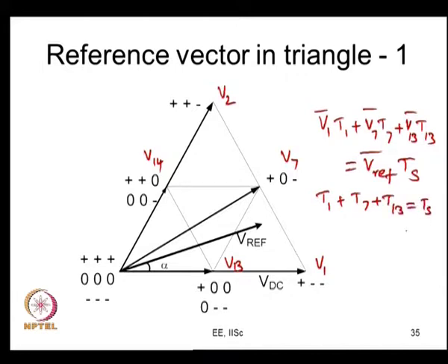The idea of volt second balance is still the same. You need 3 vectors now, and the 3 vectors have to surround the tip of the reference vector. That is important. You can actually use these 3 vectors also, which you would have used in a 2 level inverter. Now, you have another set of 3 vectors, and these are closer to this vector, and therefore the error vectors are closer, and their integrals are going to be lower, and therefore you are going to have a lesser amount of distortion in your current. So, that is the basic difference.